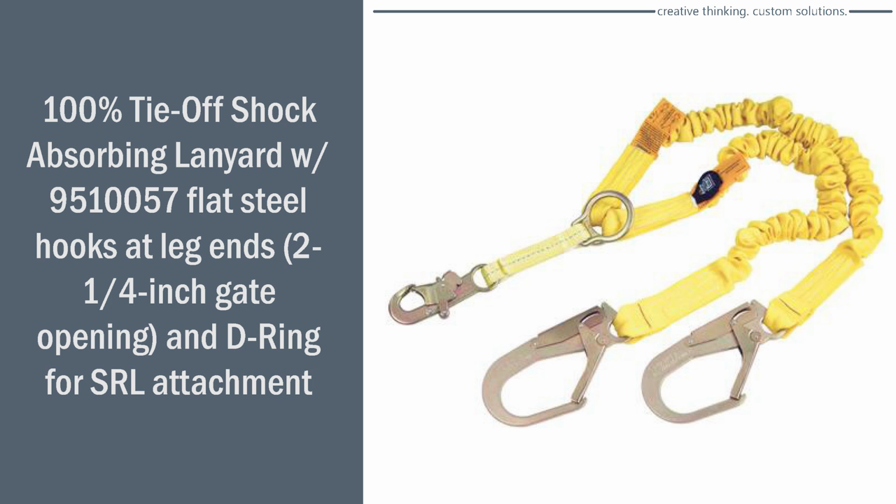Here's another one. The reason I put this picture in here is you see where all the parts of the lanyard are bunched up. If you've ever seen the inside of one of these, you'll see that this webbing up there has a lot of, I call it thread in it, so that when you fall, it starts ripping out the threads and absorbs the force, but it's still one continuous piece.